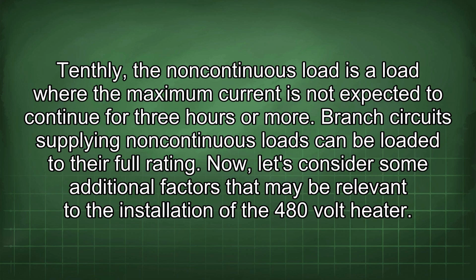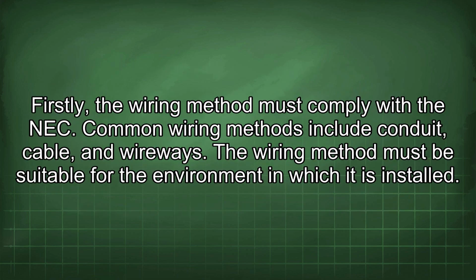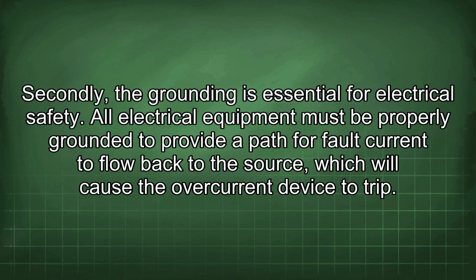Now let's consider some additional factors that may be relevant to the installation of the 480 volt heater. Firstly, the wiring method must comply with the NEC. Common wiring methods include conduit, cable, and wireways. The wiring method must be suitable for the environment in which it is installed. Secondly, the grounding is essential for electrical safety.